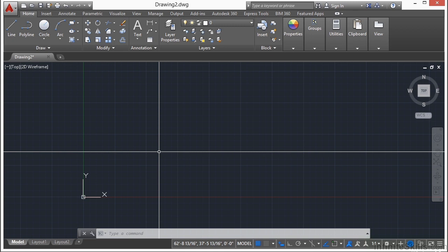If lines are single segmented objects connecting two points, then polylines are line segments in a connected sequence created as a single object. That means that they are lines or even arcs with multiple vertices. Polylines are great for drawing contour lines, wire diagrams, piping drawings, extrusion profiles, pathways, or closed objects. When a polyline is closed, it means that there is no real beginning or end. It's called a polygon, essentially, or a many-sided shape.